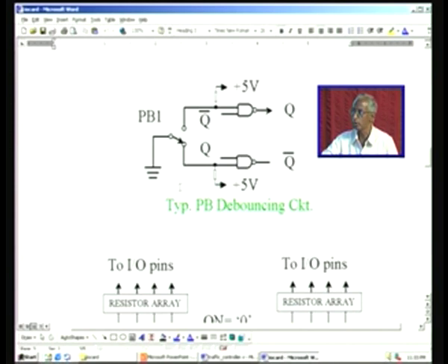Don't go for the megohms region as far as the pull up resistor is concerned, and the typical value, as I mentioned, is around 4.7K, 10K. This has been proven in industries all over the globe, and naturally if you put a smaller resistor and more similar circuitries are involved, current consumption also will be more. So, accordingly you can limit this by selecting 10K, and do not go beyond that 10K, and that is the price you may have to pay. Otherwise, you will get into trouble as far as the noise performance is concerned, and the level of zeros and ones will also give a problem.